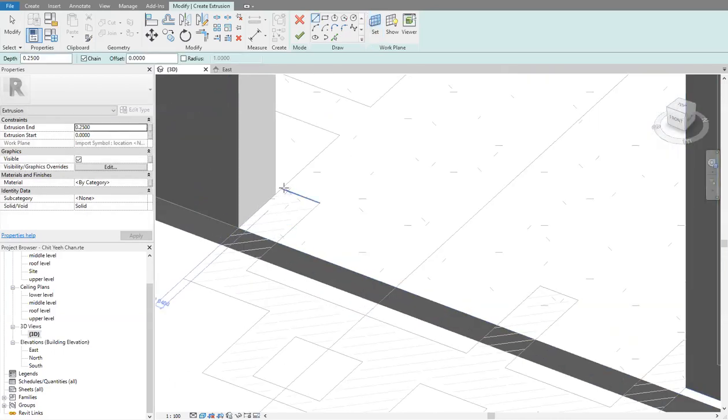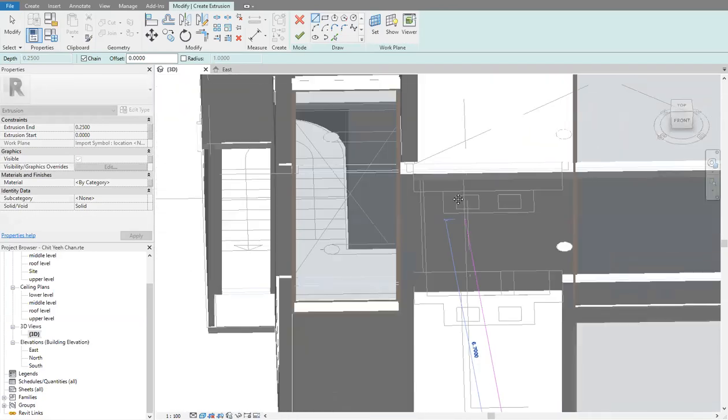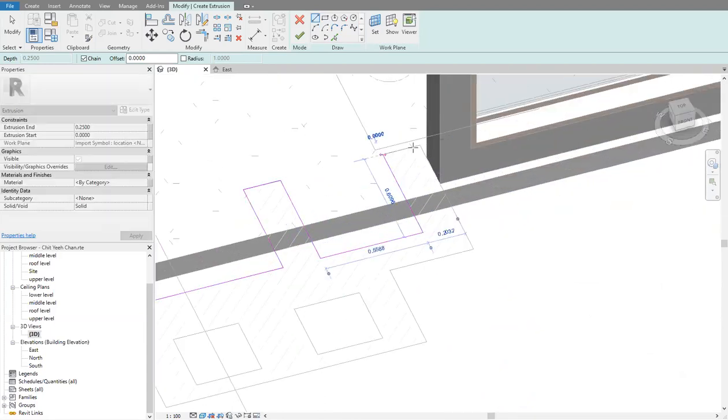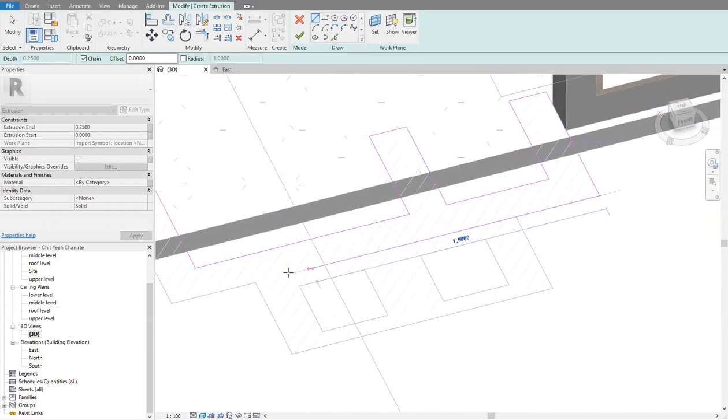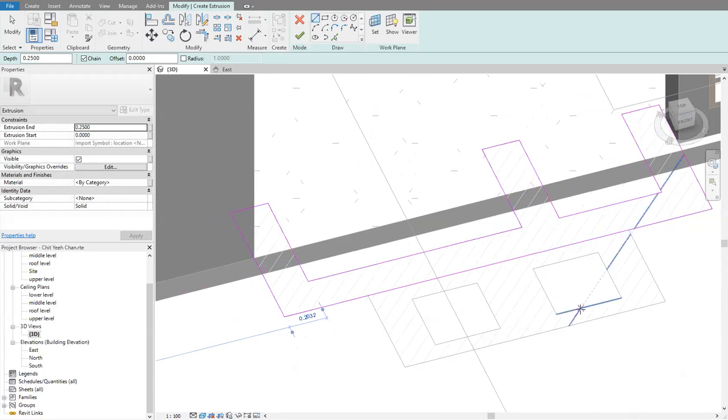So basically now, as you can see, it's snapping, and it's very important to make it snap. Otherwise, it will not be precise. So now I have the tools to draw. I will draw this shape. I follow. As you can see, I always use my keyboard to orbit. But actually, I have to go until here. I should not follow this one, because I know the height of this one will go higher.